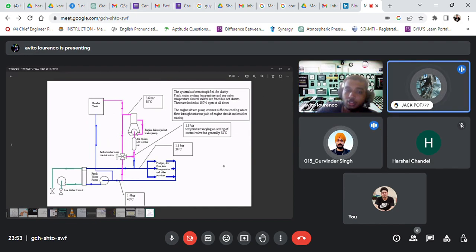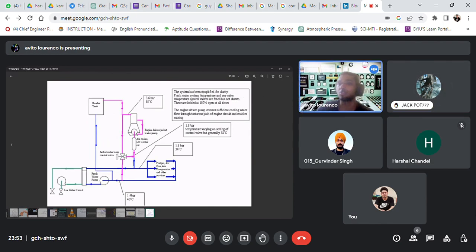Wait. I think the cursor is right. There is a three-way valve, water coming out of the main engine is going here, right? Then there is a marking over the box. Go there. Big box. Read about that. See, the freshwater system temperature control is fitted but not shown. Okay.